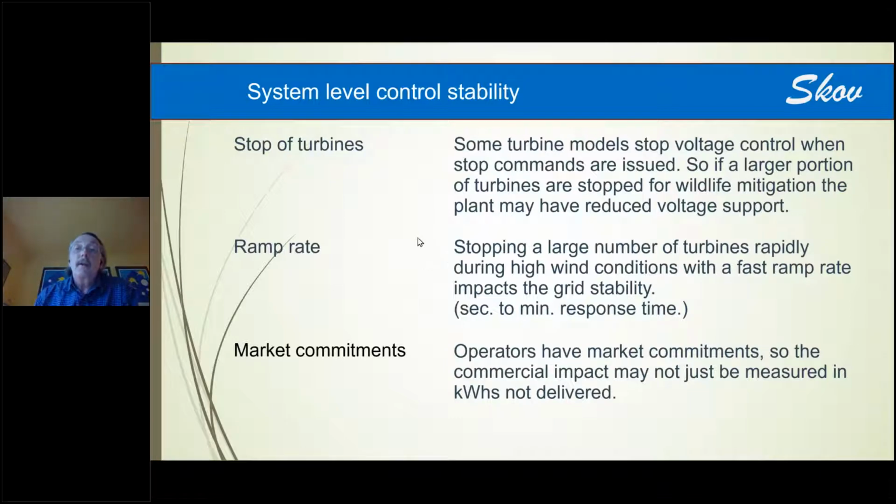So stop types, again, there are many different models of turbines, so the impact of issuing the commands will be different. And it's important to have stability. That means that when third-party companies introduce start and stop commands, they need to think about whether the duration of the command makes sense. It doesn't help to send a stop command to a turbine when you intend to have it stop for only 1 minute if it takes 5 minutes to stop, or if it takes 2 minutes or 5 minutes to start and you only give the turbine a shorter period to actually start. So there is some stability consideration when turbine manufacturers give access to these commands remotely.